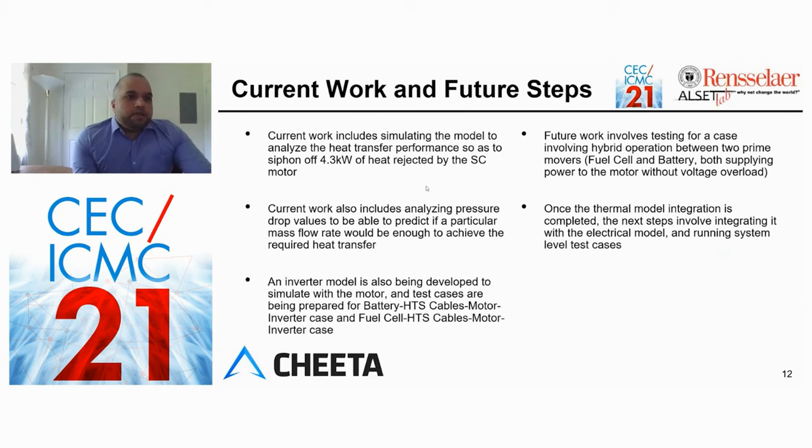Currently, work is being done to simulate this model to validate if the 4 kilowatt heat can be siphoned off and if the 4.3 kilowatt cooling budget as calculated is enough at a 9.66 grams per second boil off rate. The pressure drop values are being analyzed to validate a particular mass flow rate. An inverter model is also being developed so that test cases can be run for a power flow from the battery to the motor inverter setup and from the fuel cell through superconducting cables to the motor inverter setup.